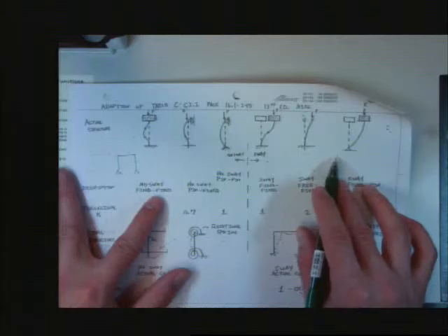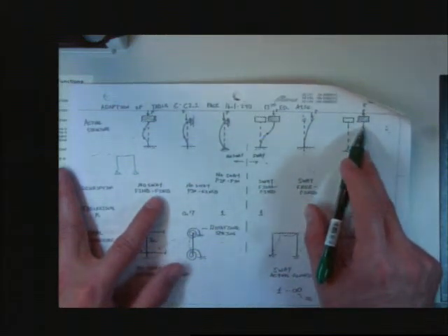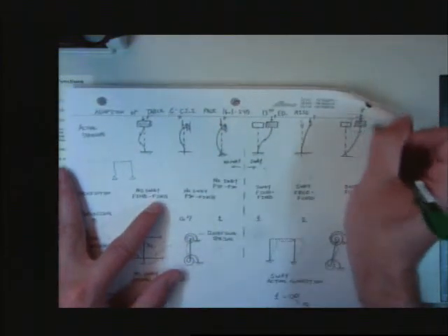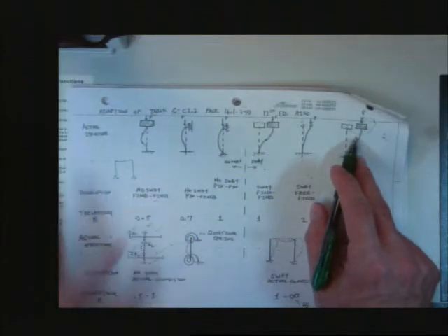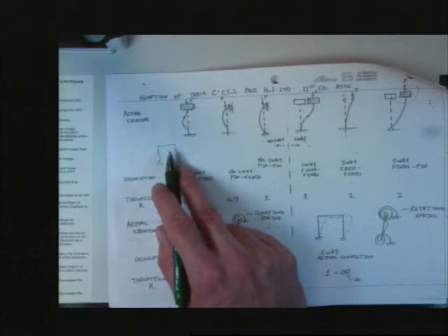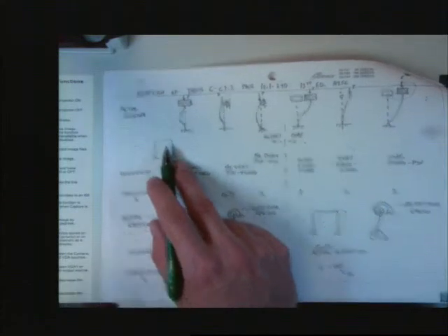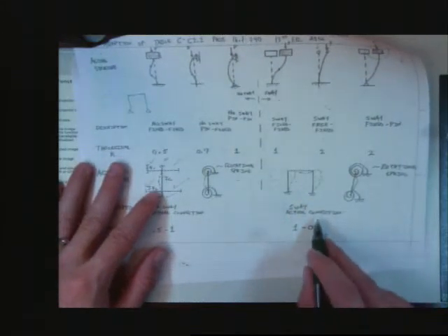What's this one, right? No! This assumes infinite stiffness at the top, doesn't it? Infinite stiffness. We don't have infinite stiffness. We have a beam. When we have a beam, we have to work it as if it's a rotational spring. It means we have to use our friend, the alignment charts.